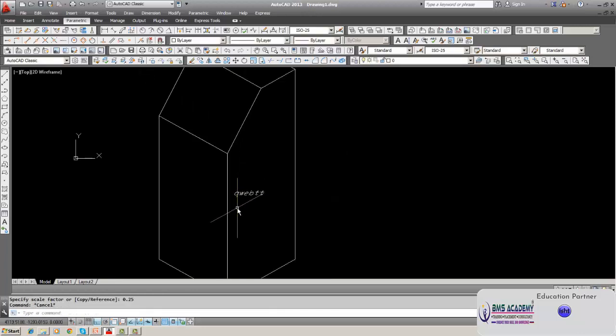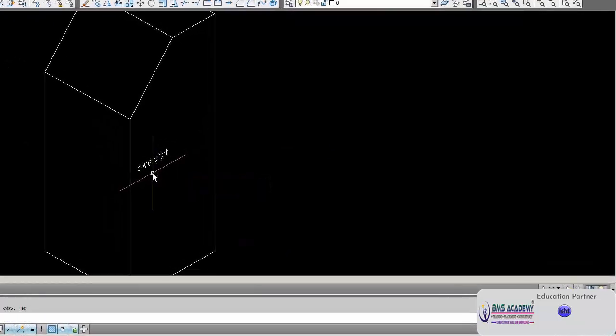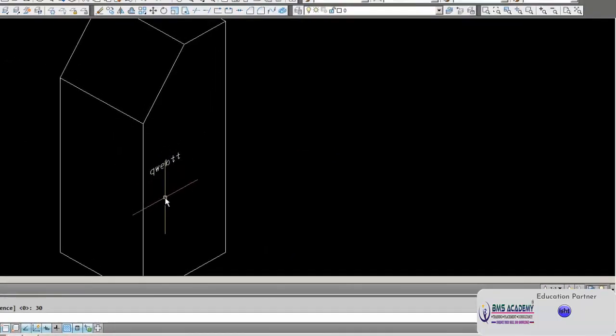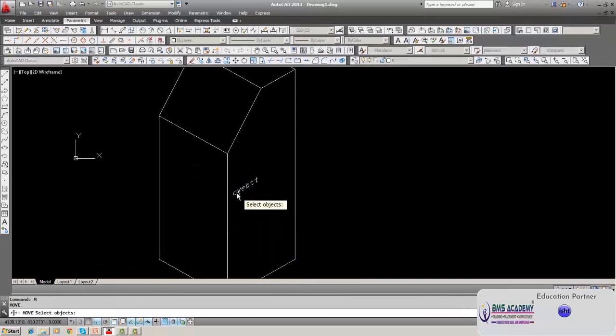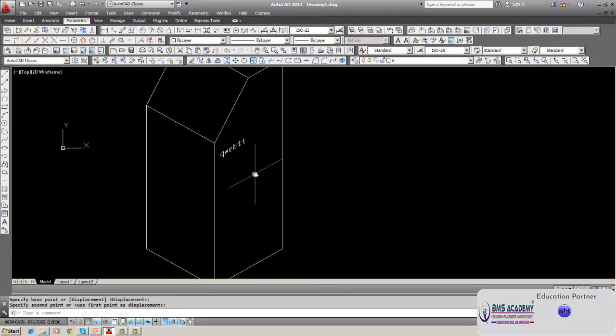Now the question is, the letters have been oriented properly, but the alignment is not oriented. For that, what we have to do, this line is inclined at 30 degrees to the horizontal, so you can orient that line. So rotate, you say, text rotate, right? Take here 30 degree, rotate. See, now it is oriented. Text is oriented in the direction.